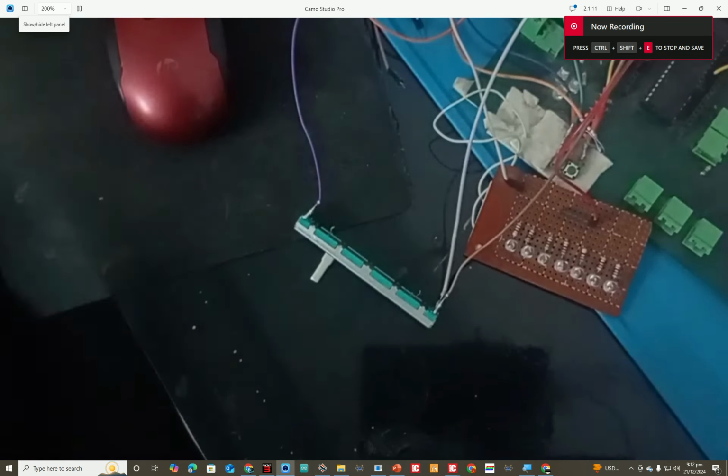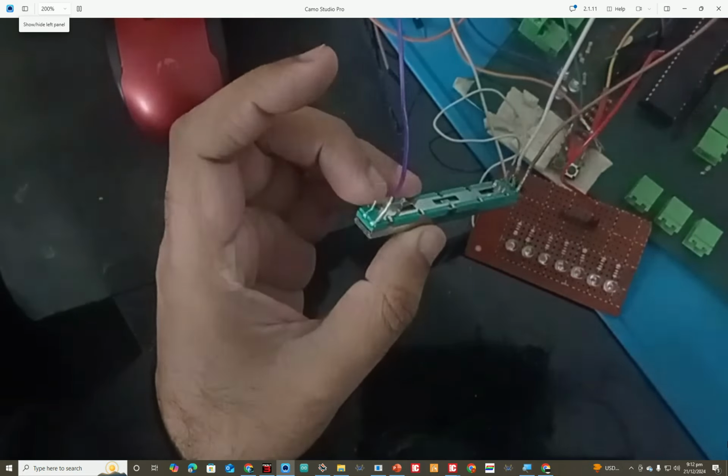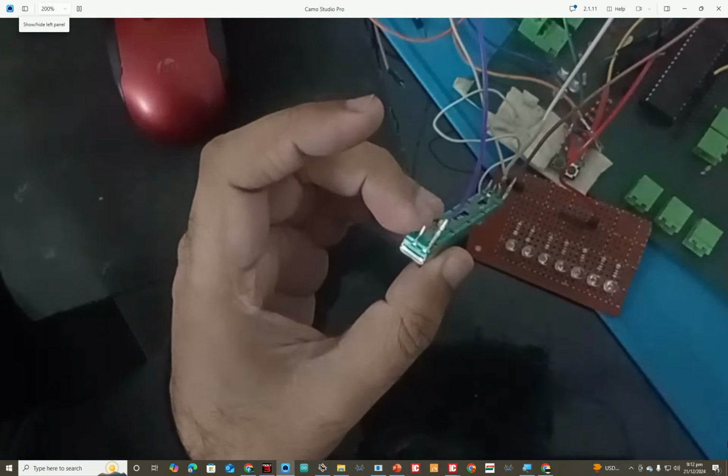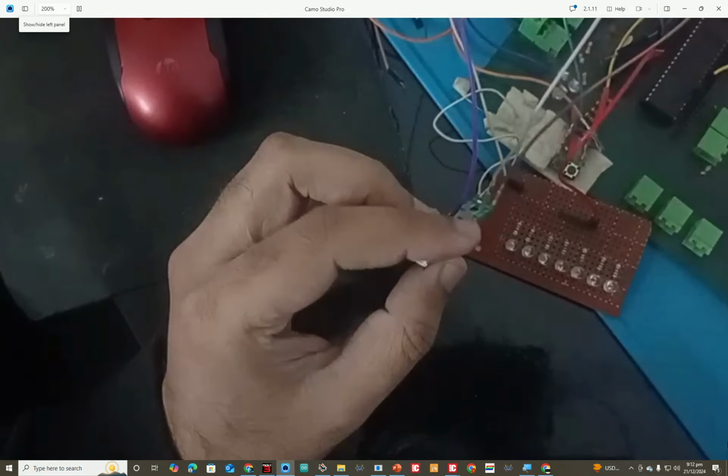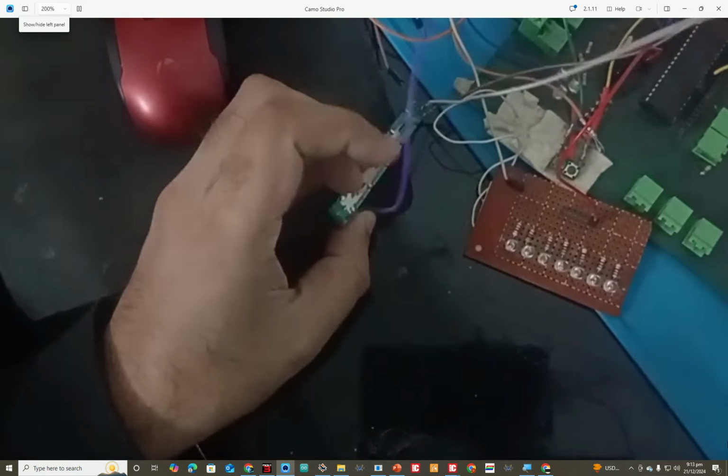So guys, this over here is the hardware. This is our slide potentiometer. Wiring is as shown in the presentation. The 2 rightmost pins are connected on the top and 1 right pin on the bottom: purple one, brown and the white. And here we have LEDs.